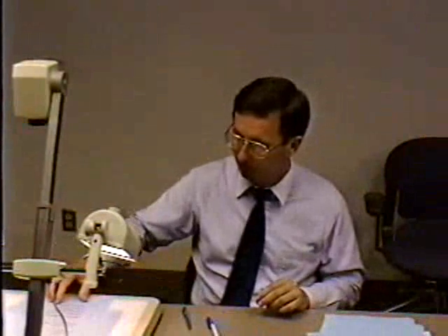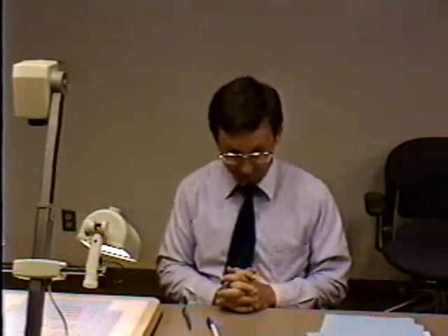What you'd really like to do is to be able to calibrate pipes, instead of using empirical data like the Moody diagram, and people will often do that in, say, a municipal pipe distribution system, if you can isolate sections of the system in which you can actually measure pressures and for given discharges, you can do calibration studies to estimate the roughness coefficients.